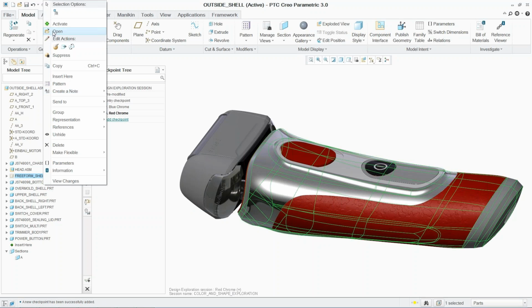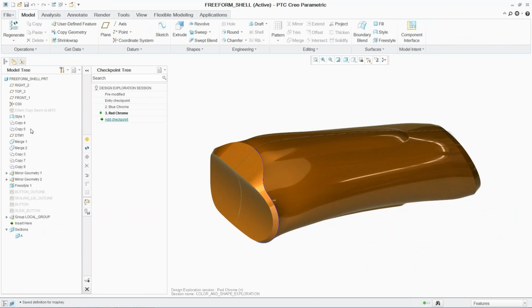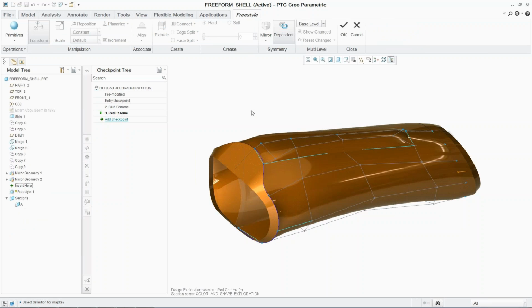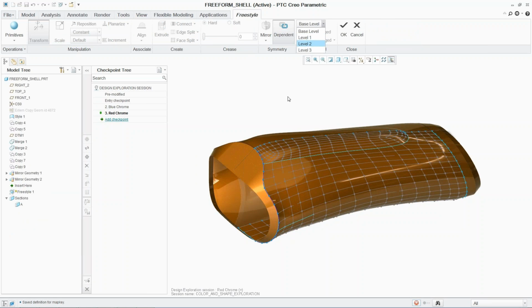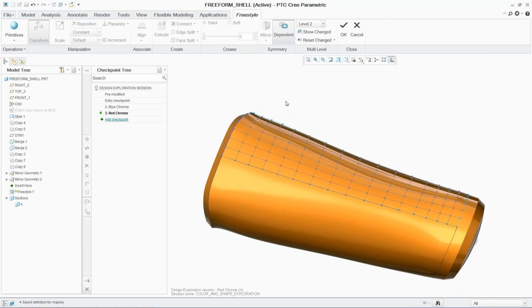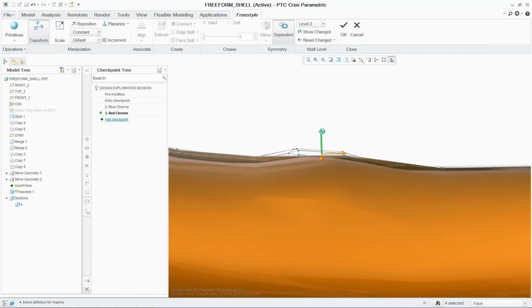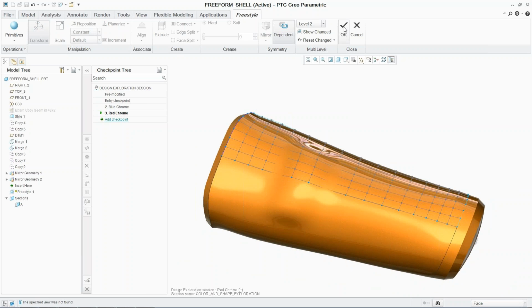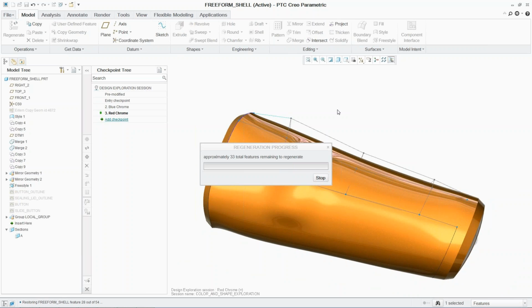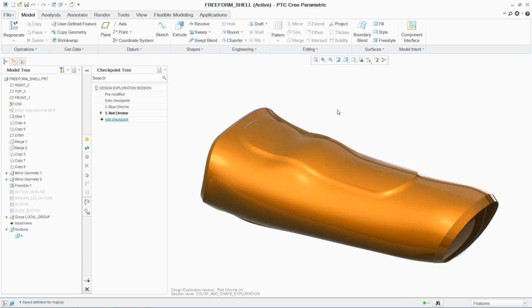If we want to do something more drastic, we can actually change the entire surface of our model. I can go in and modify some of these features. In this case, we have a freestyle feature that defines the outer shell of my razor. For anyone unfamiliar with how freestyle works, we're basically just pushing and pulling these individual nodes, edges, and faces, just to do something a little more conceptual. I'm not defining the equation that defines the curvature, I'm just pushing and pulling and making some simple change. We might want this change so that someone can rest their thumb on our razor.